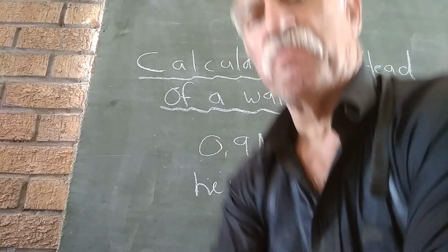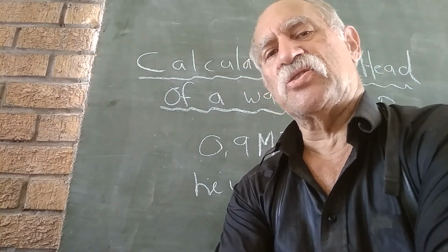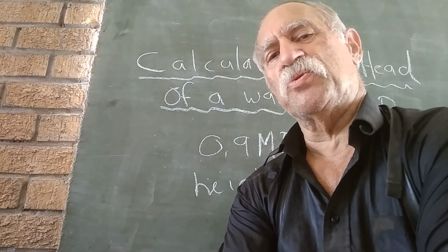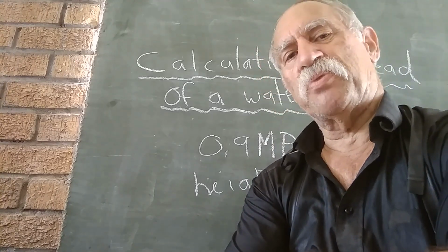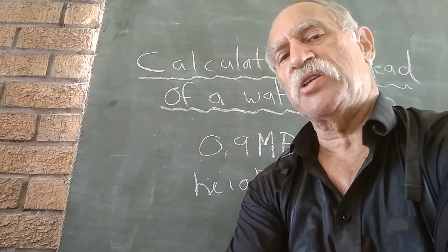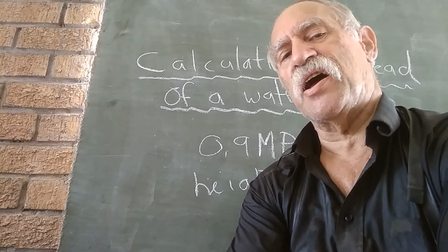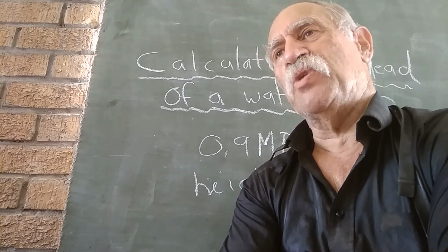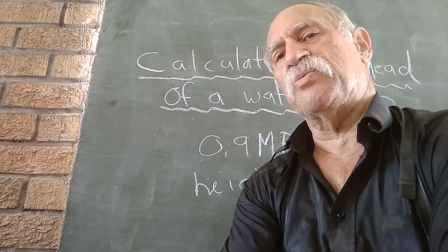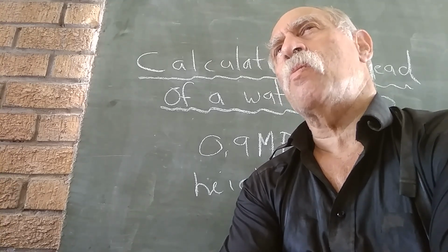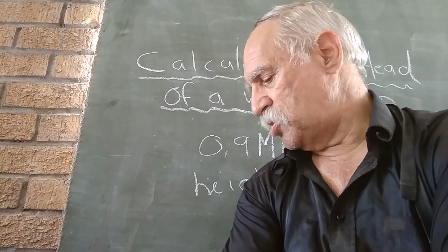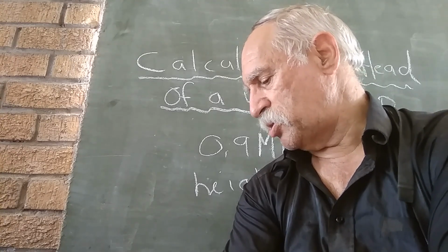That's its maximum. And then the higher the head gets, the less the volume of the water will become, I'm sure. So we know that this little pump theoretically can pump 91.7 meters height, vertical height. And we've only asked it to pump to 9 meters. So I'm actually very impressed. It actually could possibly do the job.